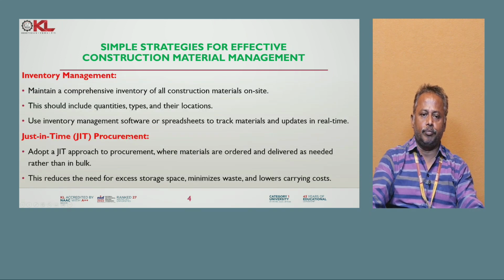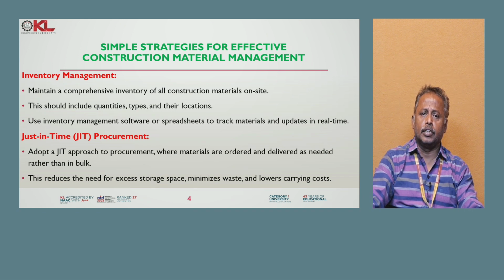So first one is inventory management. Inventory management is nothing but maintaining a comprehensive inventory of all construction material on site. It should include the quantities, the types and the location. Use inventory management software or a spreadsheet to track the material and update the real time status.